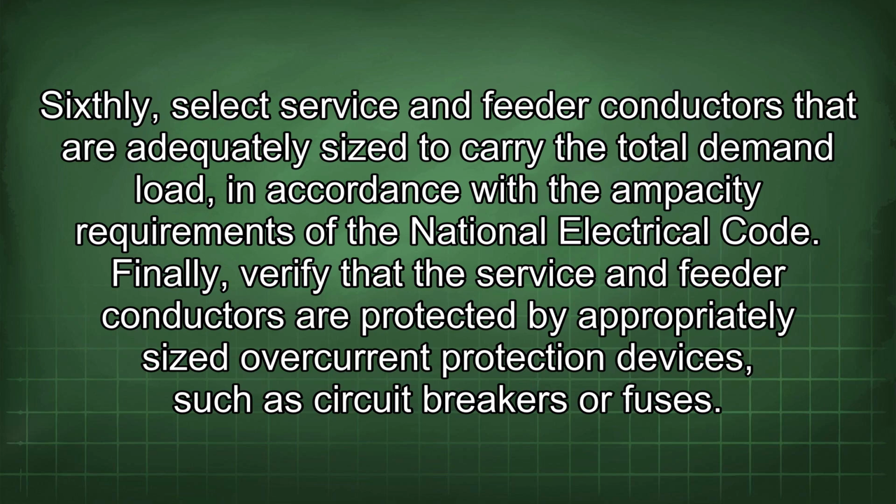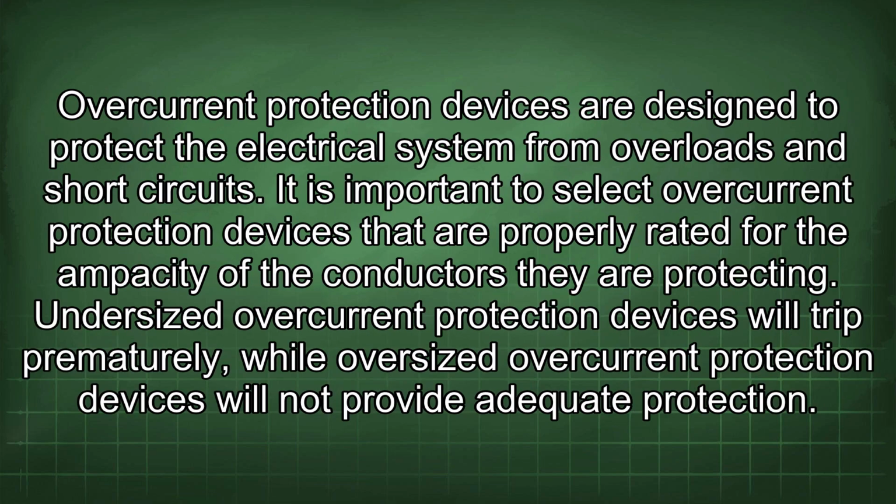Finally, verify that the service and feeder conductors are protected by appropriately sized overcurrent protection devices such as circuit breakers or fuses. Overcurrent protection devices are designed to protect the electrical system from overloads and short circuits. It is important to select overcurrent protection devices that are properly rated for the ampacity of the conductors they are protecting. Undersized overcurrent protection devices will trip prematurely, while oversized overcurrent protection devices will not provide adequate protection.